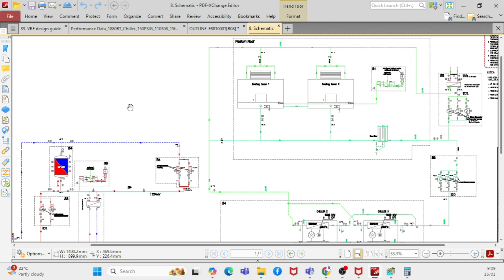Now, for the primary side, for example, you have a chilled water pump for the chiller. For each chiller you should have one primary pump, because you are going to circulate the water to the chiller, so you should match it with the chiller capacity. But here, for the cooling tower, you are not going to supply the water to a particular cooling tower. You have a common system where you can take the common water to pass through the system, so you can have multiple pumps.